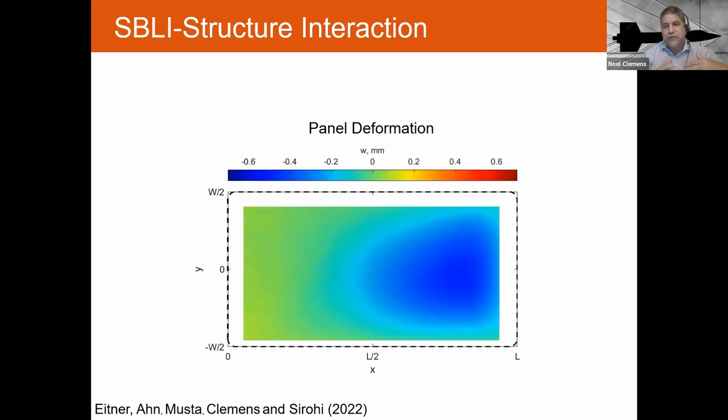We have done some work with plasma actuators where we shot pulsed plasma jets upstream, and we did show definite responses of the interaction, essentially trying to create disturbances. But it's difficult to relate those to the superstructures themselves. As for your real question, can you disrupt them, no one has been able to, or tried to do that that I know of.